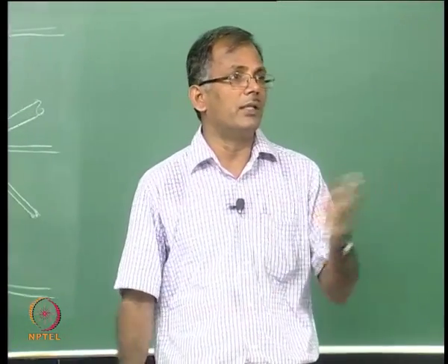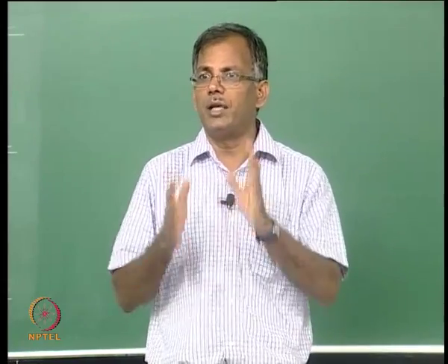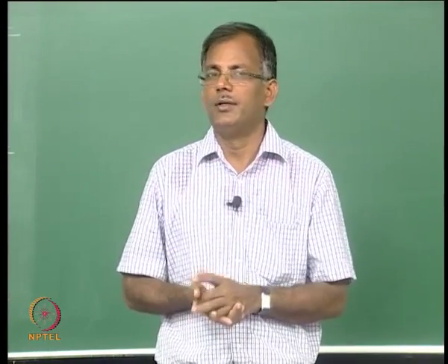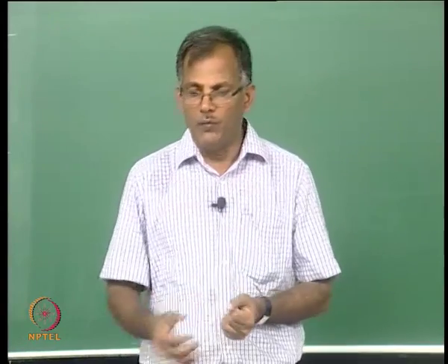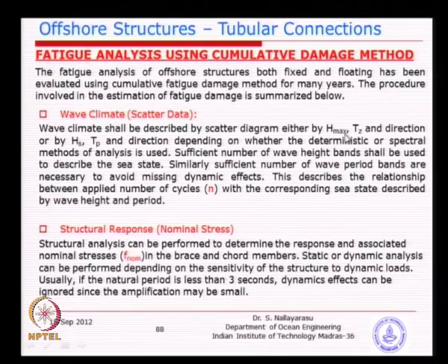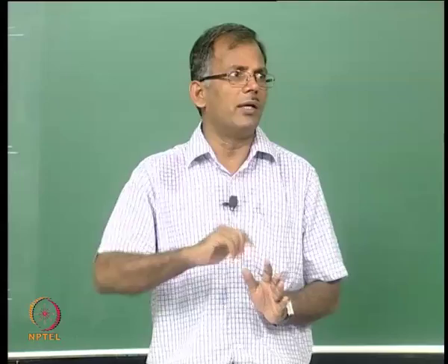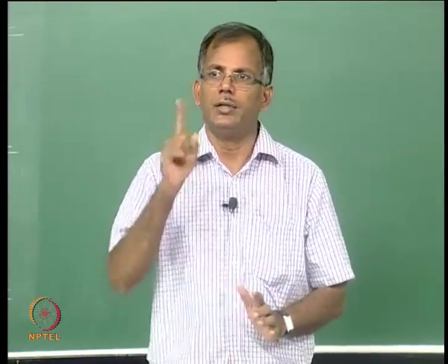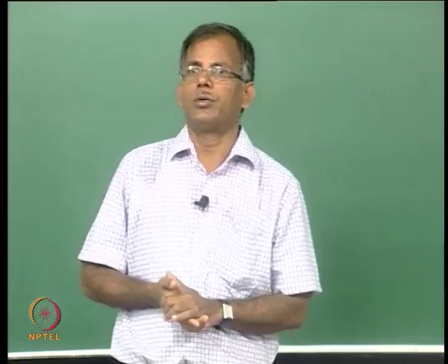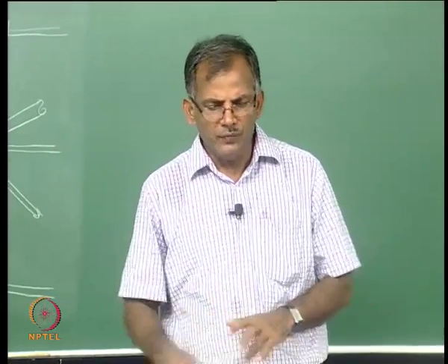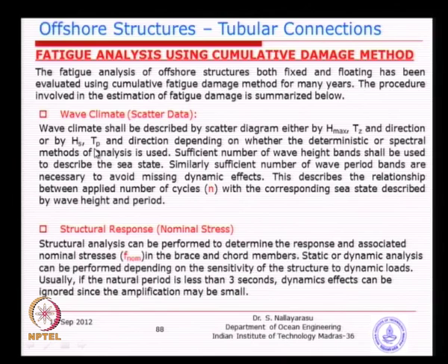I think this is what you might have studied in your hydrodynamics. The spectral distribution is normally represented by significant wave height and peak period, whereas the time history is defined by wave heights and associated zero crossing period. All of you know what is zero crossing period, no? If you draw the time history, it is the period between the zero crossing to the next one, whereas the peak period is basically a relationship between the H max, T max and the T z. You will be able to calculate using the spectral distribution. So, there are 2 ways of doing it.